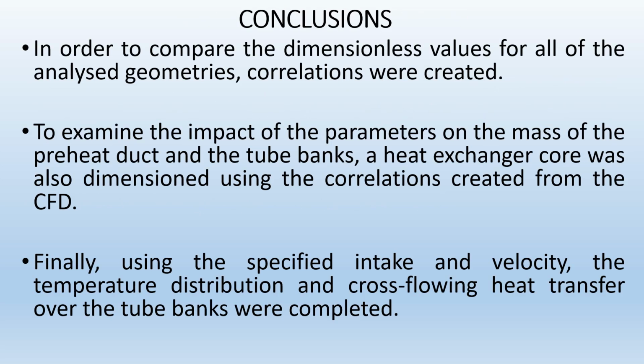Lastly, conclusion. In order to compare the dimensionless value for all of the analyzed geometries, correlations were created. To examine the impact of the parameters on the mass of the preheat duct and the tube bank, a heat exchanger core was also dimensioned using the correlations created from the CFD. Finally, using the specified intake temperature and velocity, the temperature distribution and cross-flow heat transfer over the tube bank were completed.